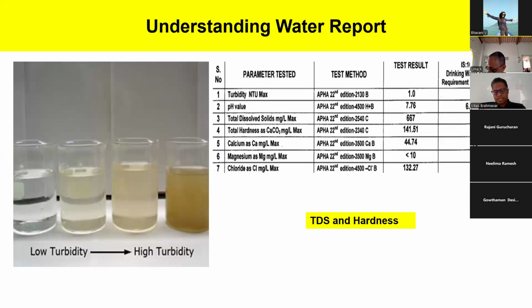The meter passes electricity through the water and arrives at a conductivity value, and the total dissolved salts value is indicated from it. So it indicates how much salt is present in the water. We should be clear that it indicates the salt level, not the purity, but it is used to a very large extent for purity measurement. When people sell RO purifiers, this is the value that changes, so they have to show something which changes. They end up showing total dissolved salts, TDS.